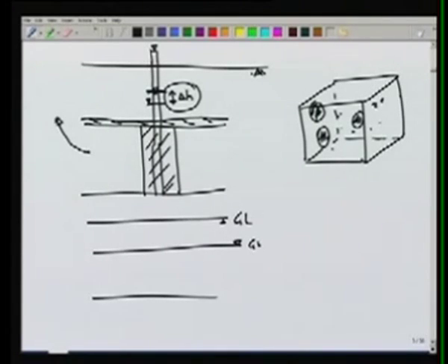This is the groundwater table, bedrock. Now if we lower the groundwater table by some amount, delta H, water will come out because of drainage of this volume. But in confined aquifers, there is no change or not much change in volume. There is little change which we will see, but there is not much change in the volume.